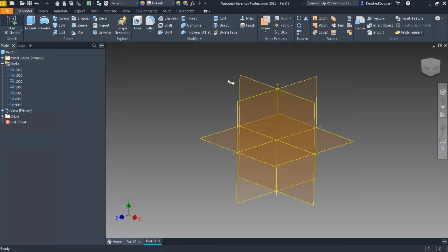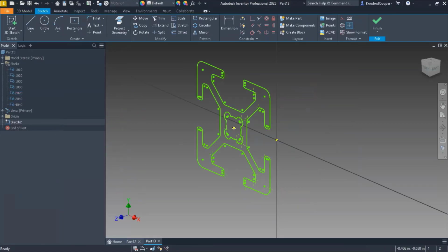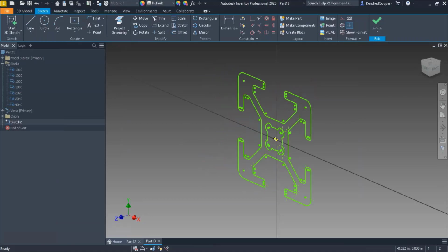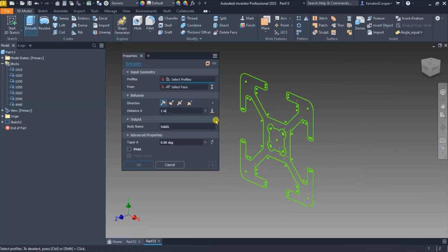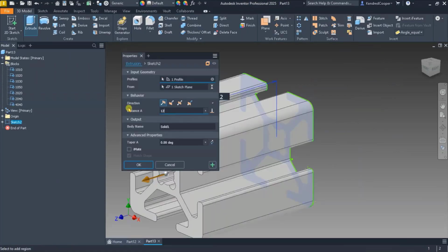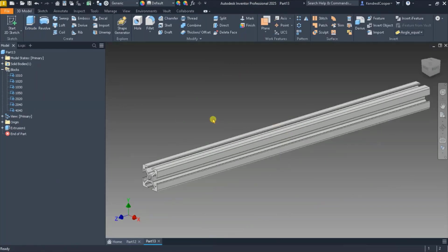So very quickly, I can start a sketch, locate a block I want to use, right click on it, place that block. There's all of my sketch geometry already there. Constrain it, finish my sketch, and immediately extrude it to whatever length I need. You build these into the template by opening the template itself and defining the geometry from there. So you would not click on new for this operation.